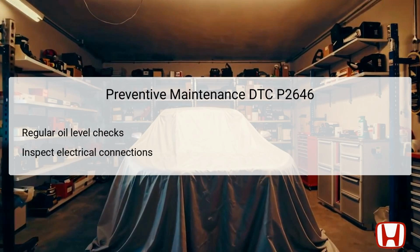Preventive maintenance plays a pivotal role in avoiding issues like DTC P2646 in the future. Regularly checking and maintaining the engine oil at appropriate levels is vital for ensuring the proper functionality of the VTEC system. Low oil levels can lead to severe performance issues and engine damage over time. Furthermore, inspecting the electrical connections at the rocker arm oil pressure switch and the PCM should also be a routine part of vehicle maintenance. Ensuring these connections are clean, secure, and free of corrosion can help prevent intermittent failures or short circuits that could trigger DTCs in the future.